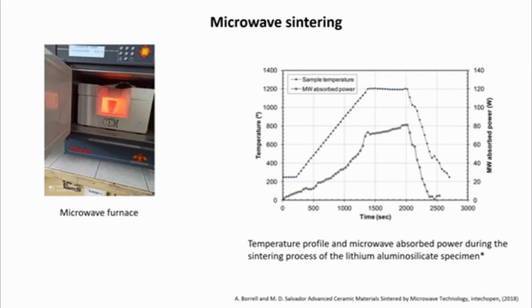Microwaves have been used since the 1960s for heating purposes, particularly for food and water-based products. Industrially, the use of microwave energy has become increasingly important because it represents an alternative to traditional high-temperature processes. For example, so far it has been employed in wood drying, resin curing, and polymer synthesis. The growing interest in industrial microwave heating is due mostly to the reduction of production costs, resulting from lower energy consumption and shorter processing times.